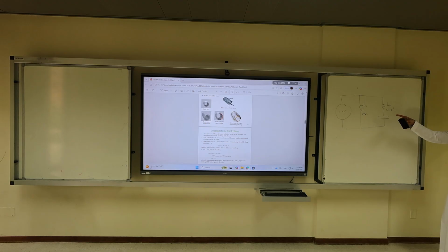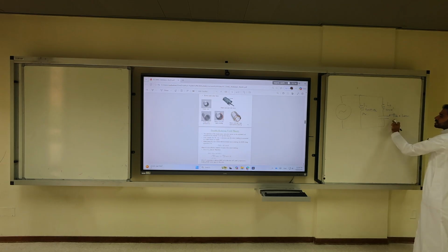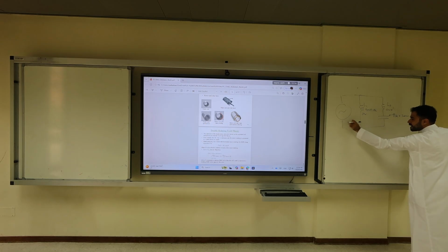It will be the phase shift due to the auxiliary inductor and due to the capacitor. So maybe I would have here 90 plus something, 90 because of the capacitor. And here I have something else. But now I can run them using a single phase source,